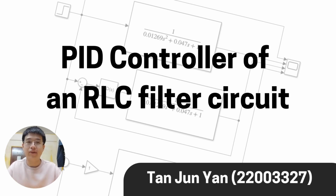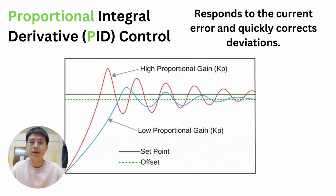A PID calculates the error, the difference between the actual value and the desired value, and then sets the deciding parameters accordingly. This error is continuously being calculated until the process stops. For the proportional term, adjustment is made in real time based on the current error, which helps in quickly correcting deviations.